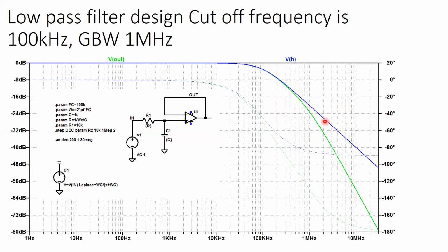But then as you get farther and farther, the gains are wildly changing. And here's the thing, that gain bandwidth changes a lot for manufacturing. So you might say, yeah, this is a better low pass filter. Look, I'm getting a second order filter for one capacitor. Well, maybe. But if you're making thousands and thousands of products and they're not all working the same, you might find that you don't want to do it that way.